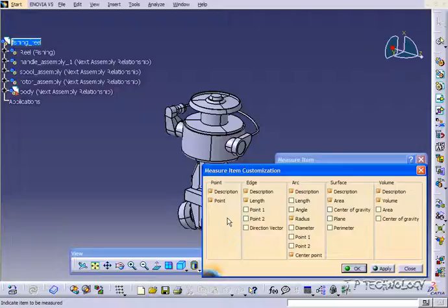Because you're also able to choose like a part and faces by itself, you're going to be able to take the surface and the volume, and you're also able to get dimensions for those too. So when you select an object, it's going to take whatever is viable for it. So if you choose a line, it's not going to tell you the area because there's not going to be any area to the line. It'll just tell you the length. So you're able to change any of these if you want to. For now, just leave it alone.